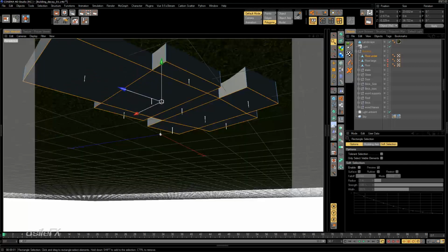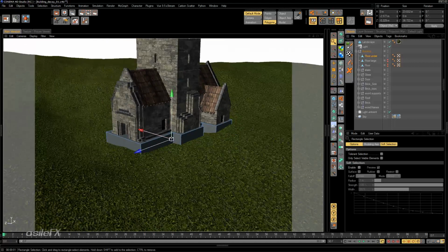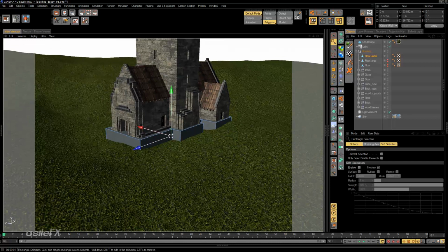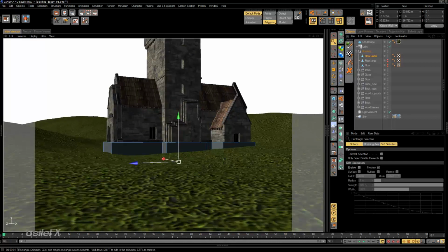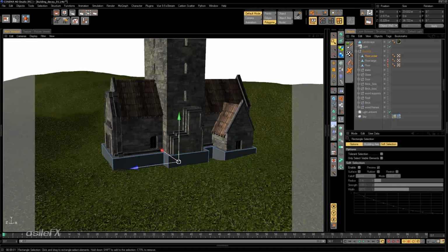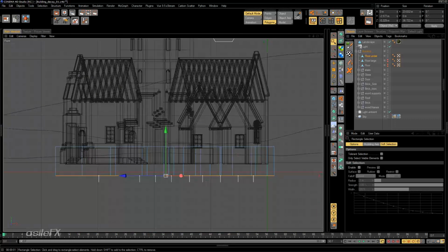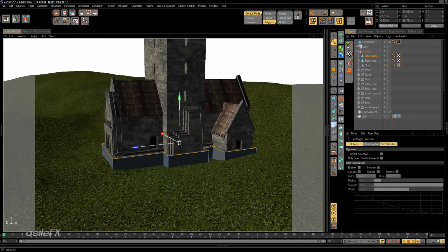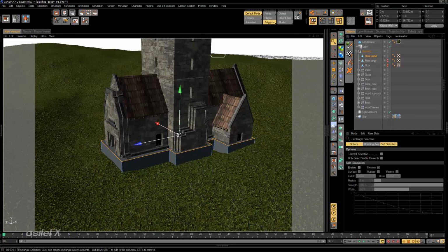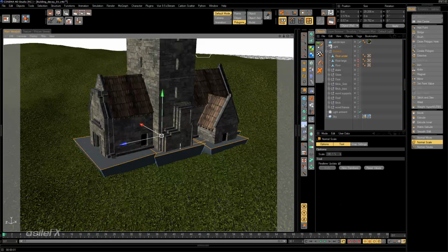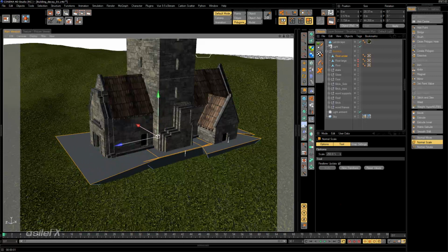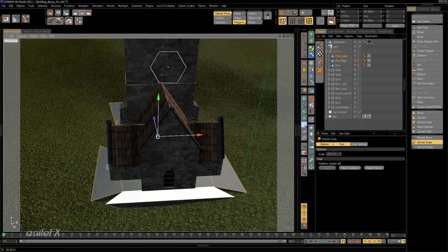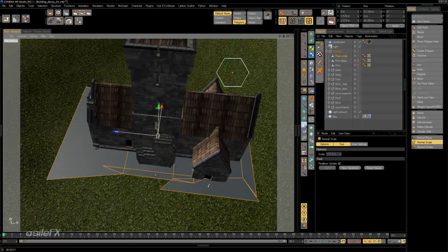So our goal with these bottom polygons is to taper out the edge in order to give us the fall-off range that we need. And actually, now that I think about it, unless I want to populate only around this object, I am going to need the top set of polygons and not the bottom. So I'm going to take these and I'm going to use the normal scale and just scale them all up until they're almost all intersecting.